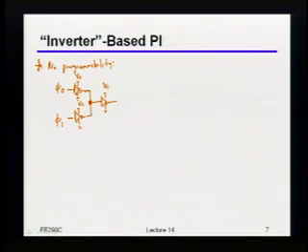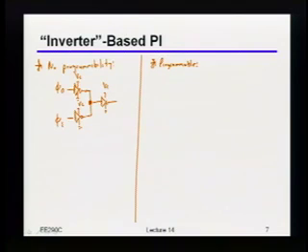Okay. Now, by the way, once you've done the phase interpolation, after that you can be at whatever supply voltage you want. Now you can get as clean of an edge as you'd like. Okay, so if that's the way I would build a phase interpolator, period, how do you build a programmable phase interpolator using inverters? It doesn't have to be exactly inverters, by the way. Obviously, we're going to have to hack them a bit. How do you do that? What do you guys think?